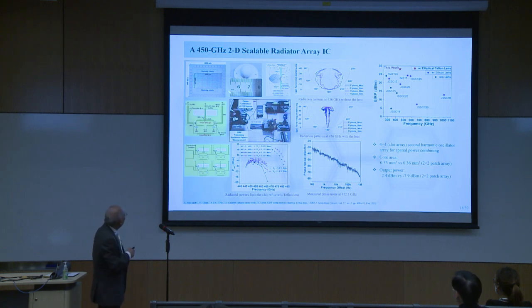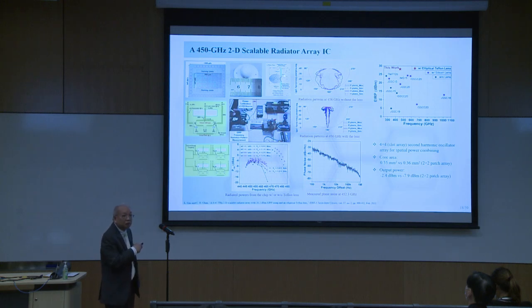And next, we designed a 4x4 radiator IC. You can see that by carefully placing the slot antenna elements to reduce the backscattering as well as the generation of surface waves, we can have the IC radiating, and then we place an inexpensive Teflon lens, which was fabricated in Shenzhen through Taobao and only costs about 500 RMB, compared with the several thousand US dollar silicon lens used by other people.